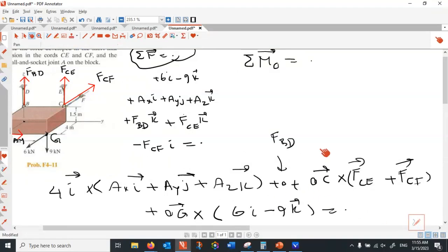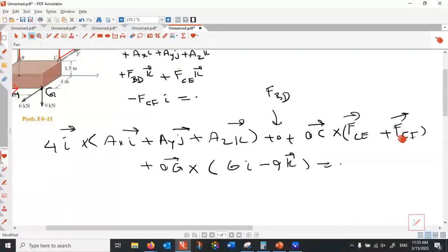All right, so this is another vector equation. That vector equation, how many scalar equations is a vector equation? That's 3 equations, because you collect all the I components and set that equal to 0, collect all J components and set that to 0, and the K components. So if you solve these two systems of equations, you have 6 equations, 6 unknowns, and that is solvable.